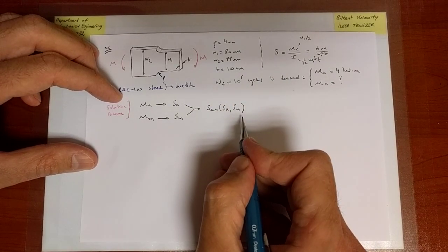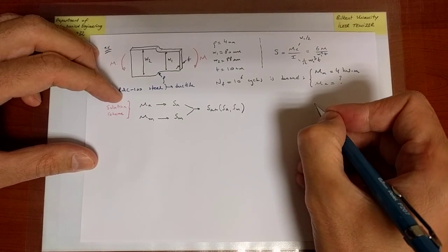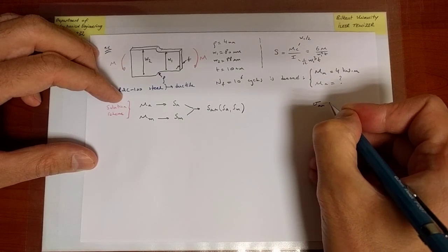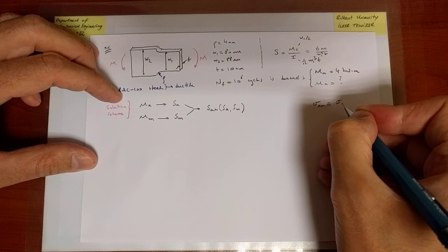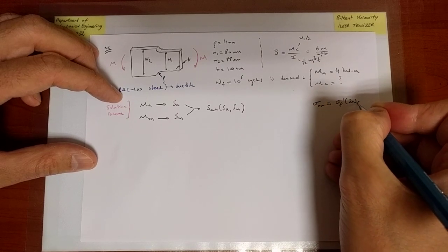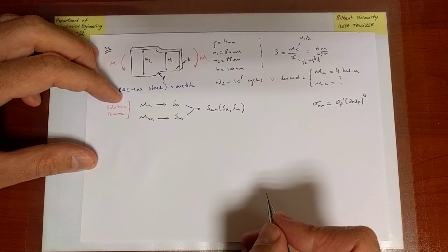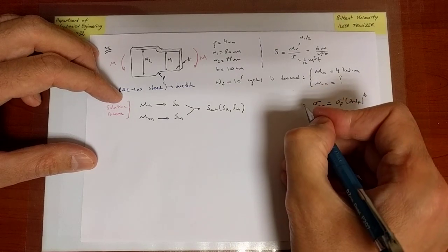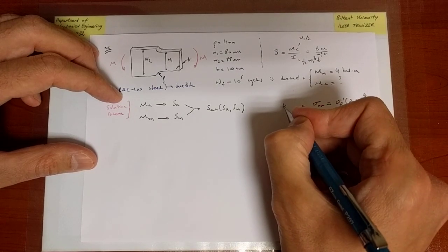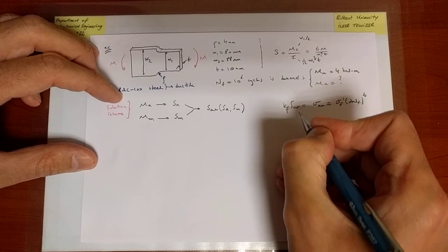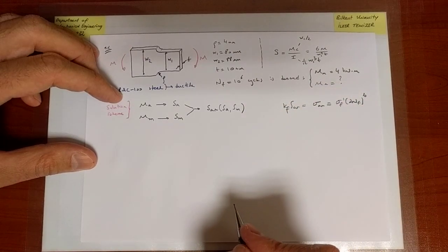But that's not what we apply in the Basquin equation. In the Basquin equation, I need the point stress, which is associated with life through the classical Basquin form. And the point stress is a factor times the nominal completely reversed stress amplitude.